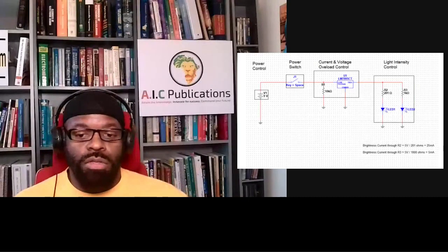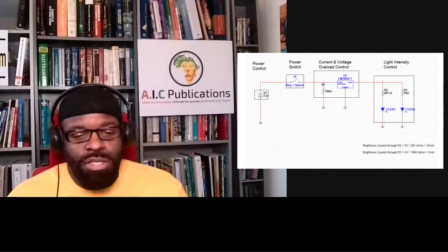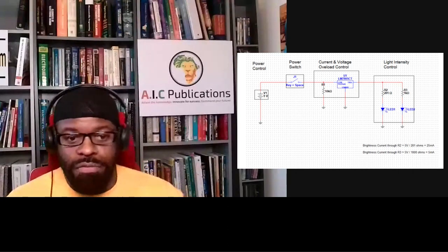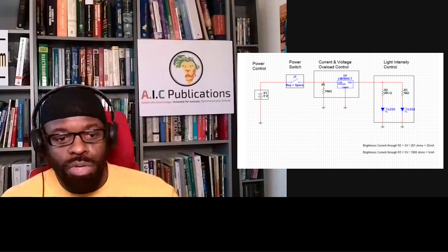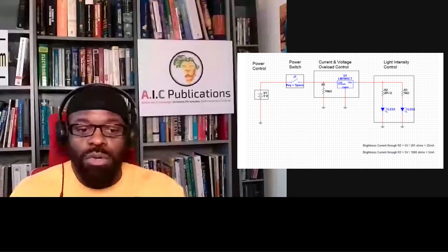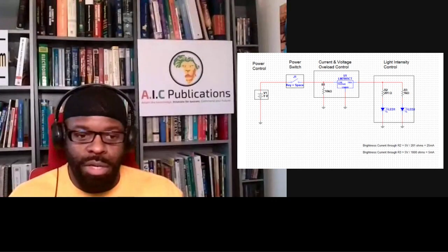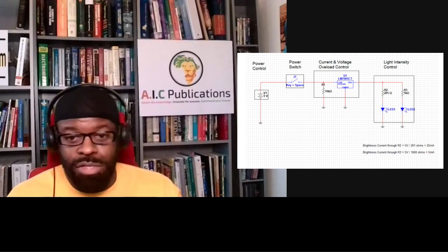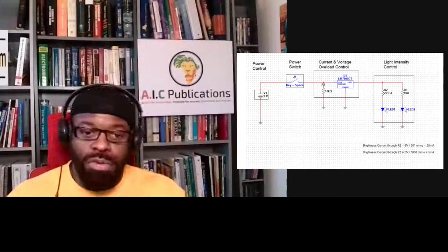Now, in this particular circuit, when we're talking about lighting two different places with two different brightness levels, this is the first block that we have. We're coming off with a 9-volt battery source. We're putting that into a switch. We're connecting that 9-volt battery into a switch because if we don't do that, then the battery source will always constantly be on, and you're always going to have to change the battery because it's going to run out of power. It's going to run out of current. It's just going to be looping all the time and it's going to be on. It's like leaving a light on that never turns off.